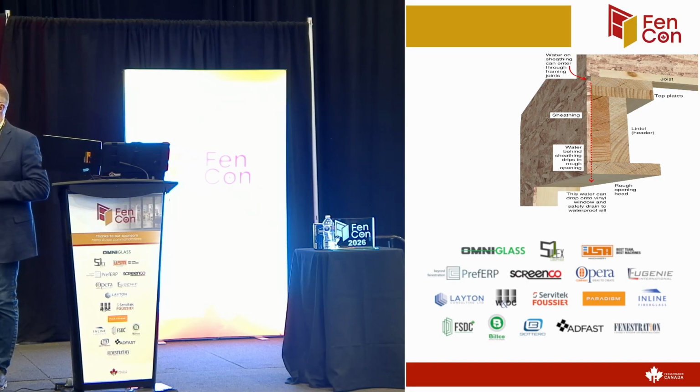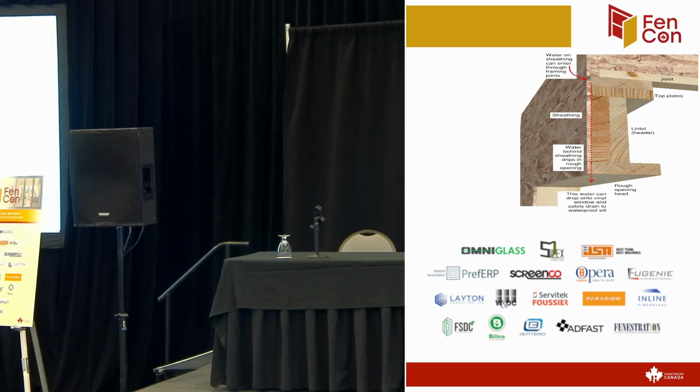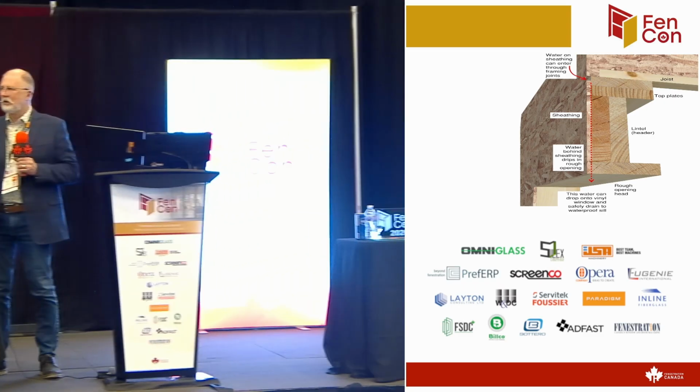I think it's actually a bit of a misnomer that you even need to worry about the caulking on 3 sides. If you've got a continuous interior seal that stops the air, and a water shedding surface to the outside, the inside can still manage it. As a matter of fact, there's probably some arguments about equalization of that chamber that actually come into play. Yep. I agree. So if you think of the pressure drop, never have the pressure drop in the same plane as the drainage. Right? Never.